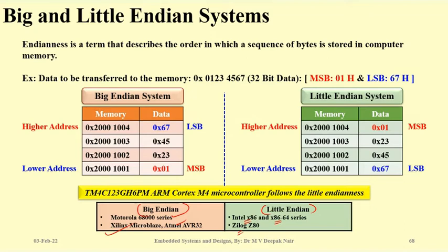They use little Endian. So this is very important to understand, because when you are going through the memory and decoding the data in the memory, many times people get confused about why the stack is following this particular approach and memory is following that approach. So you have to have knowledge of the Endianness of the system.